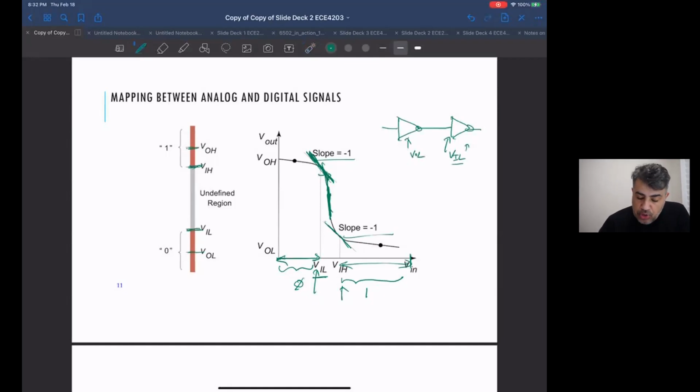You would like the output low to be all the way to ground, but the reality is your output can't go any lower because of your inverter. A CMOS inverter can go all the way to ground, but the inverter you're designing now cannot. So there's no point saying that's part of my noise margin.